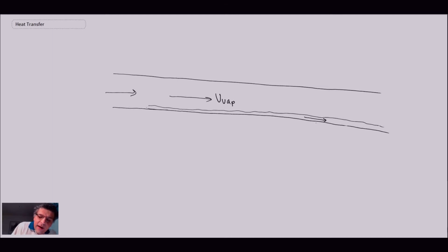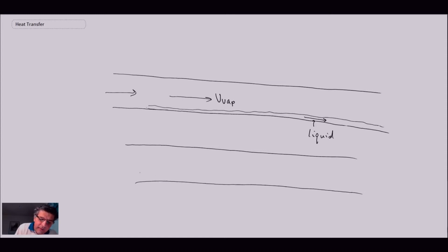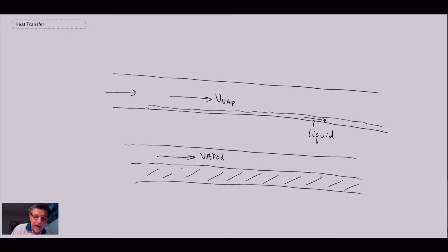But essentially what happens is this here would be your liquid, and you would have gravity driving that. You want to be careful because as the tube gets more and more liquid building up, eventually you're going to get to some point like this. Ideally, you want to keep it as being stably stratified flow. And so you'll have your vapor up here going through. This is if we have what we refer to as being tube-side condensation.